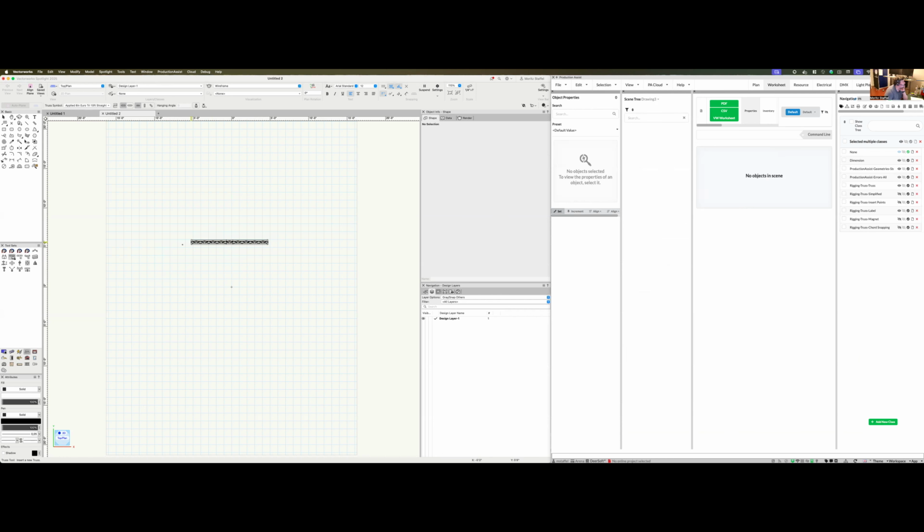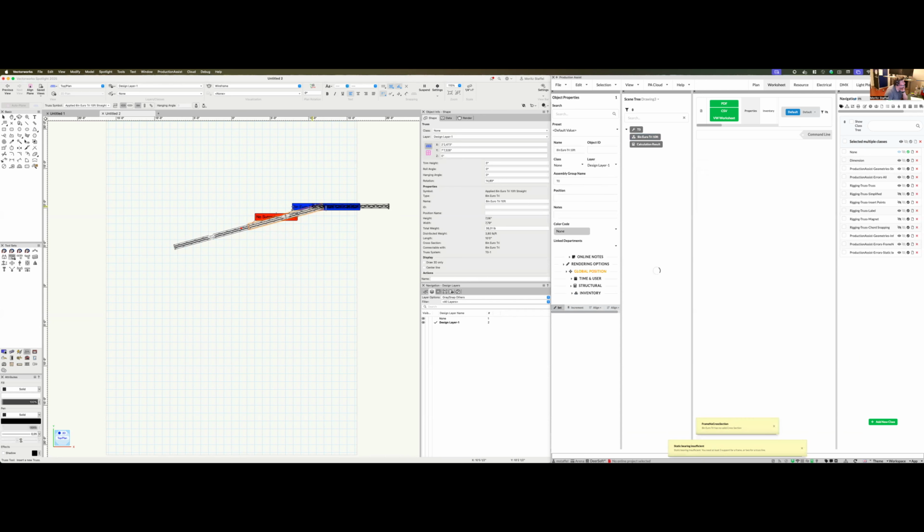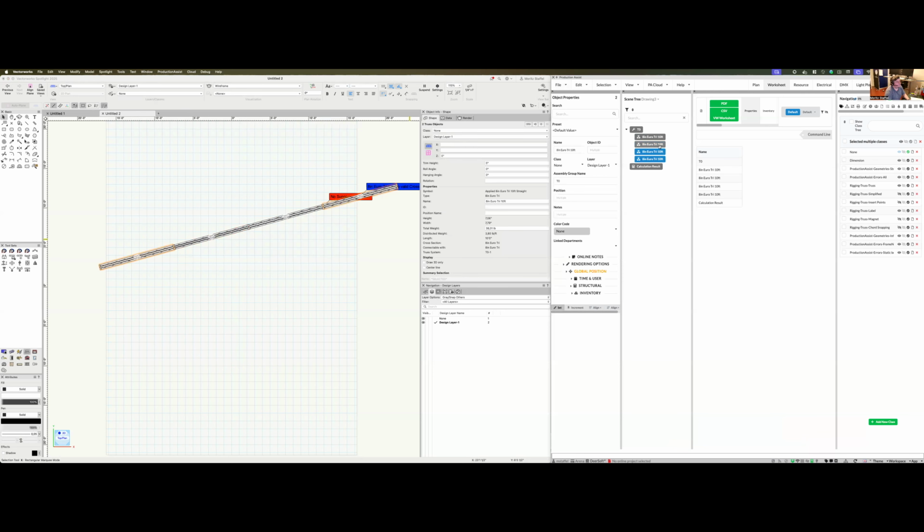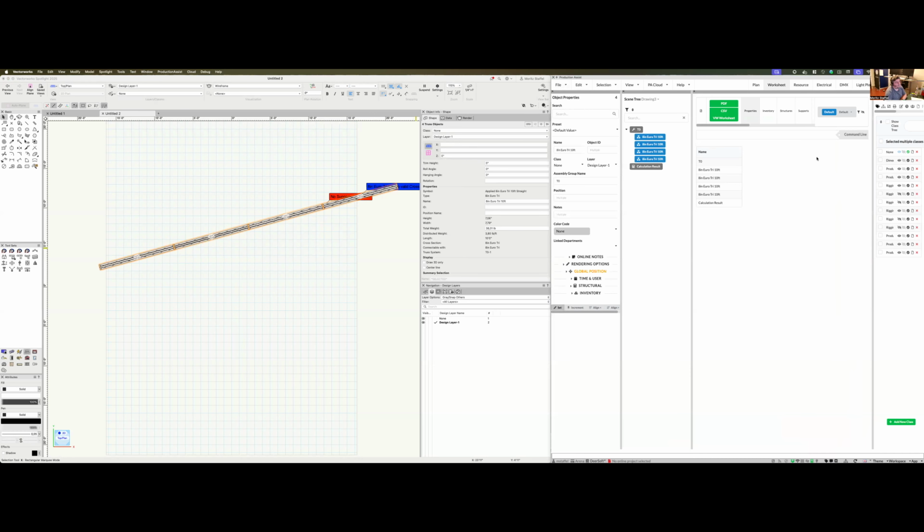On the left side, the scene tree organizes your objects into groups, making it simple to select, edit, and manage trusses and hoists. It allows you to select objects just like in the Finder or the Windows Explorer. The selection is synced with Vectorworks. So when you select something in here, it becomes selected in Vectorworks and the other way around. Meanwhile, the table view provides a comprehensive overview of key parameters like assembly groups, weight, and load values, helping you monitor your entire system in one look.